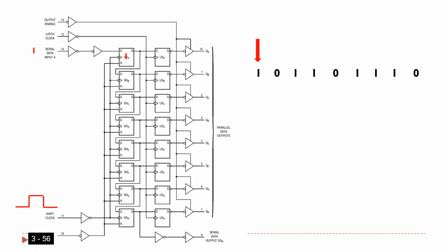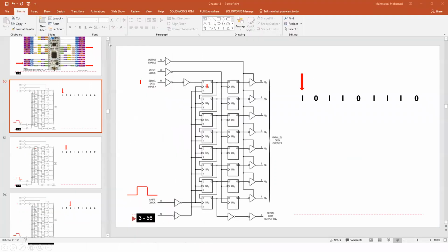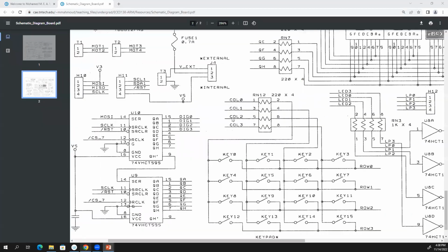Is that okay? And again, this is how the people who made the board made it. As you see here, guys, we need 2, and you should understand why we need 2. In this one we have 8. Out of this 8, we need only 4 for enable. So this will be the common cathode. Any one of these, if I make it 1 or 5 volt, you actually enable.